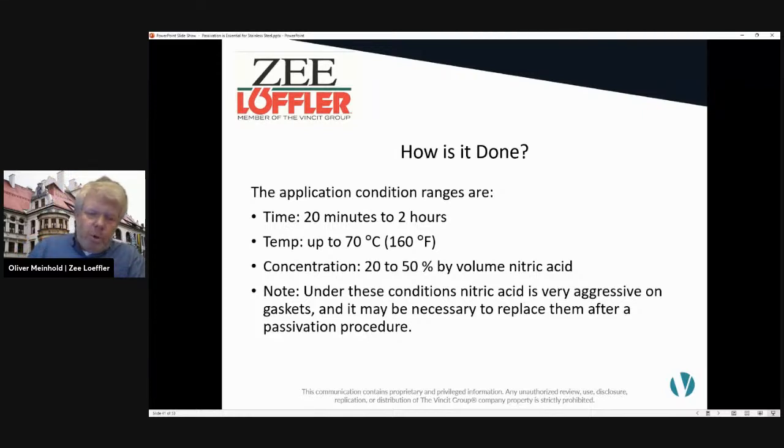In a perfect world, when you did all the pre-cleaning perfectly, your nitric acid solution shouldn't change in color. Otherwise, you have something dissolved, which then is in the acid. You should also ensure that there are no other particles inside. That means either you dissolved something or the cleaning has not been fully done.